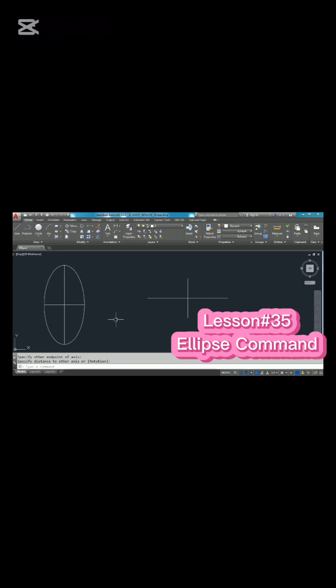Let us use the same command and pick 3 different points over here. Type EL at the command prompt and press enter. Now it is asking to specify the axis endpoint of the ellipse. I am picking over here as the first point.